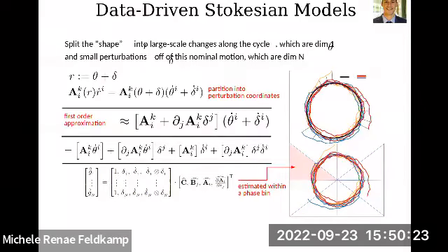And because delta is small, I can take this equation here, which is what I'm trying to model, partition it, and then do a first order approximation. This is just Taylor series. This is nothing fancy at all. I do the Taylor series, I multiply everything out, I end up with a linear regression. And it's not a terrible linear regression to do. I do this in each of these segments, and now I have a physics model that's computed entirely from the data. Okay, I basically learned the physics of my robot by observing.